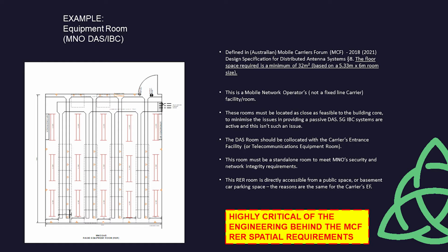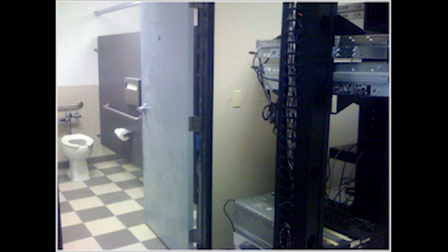It is important at the high-level concept design stage to determine the demand estimates for equipment for the purposes of incoming supply and climate control assessment. It is reasonable to tentatively allow 1.5 kilowatts per rack, inclusive of the passive cabling racks.